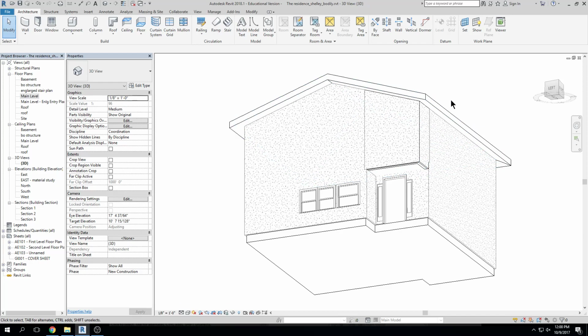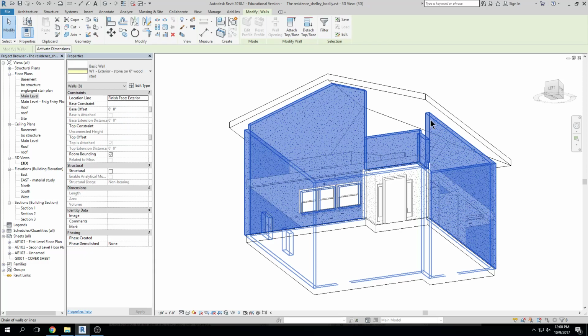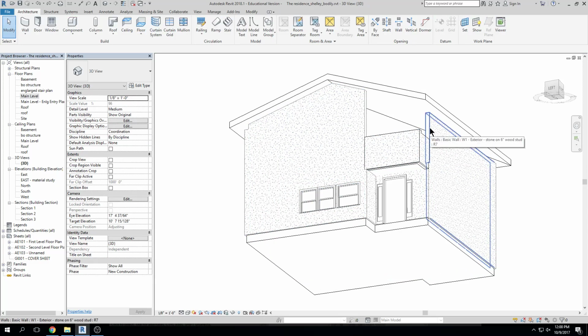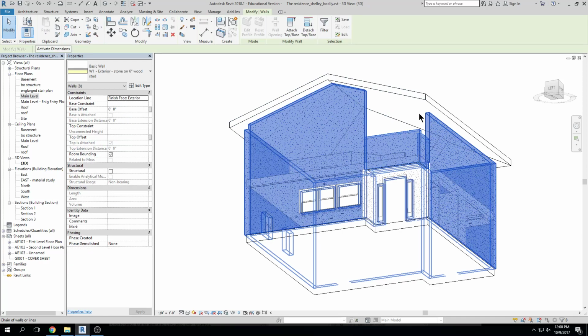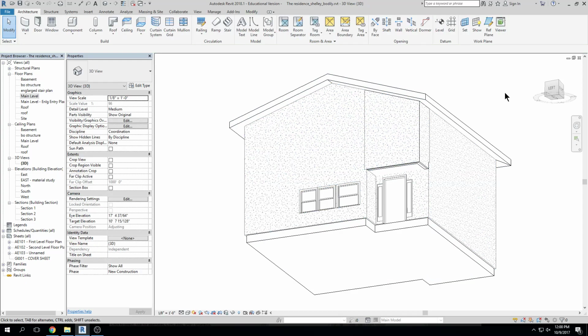The object. Yep, that's a good question. Let me undo, because this is always a tricky thing, right? I hover, I'm highlighting it blue, but I'm not clicking, but I'm on the object. I tab, whatever is touching that object in the chain, it selects, and I click. I don't move my mouse. Click. If I hover and I tab, and then I move my mouse, it essentially breaks that connection. Yep, hover, tab, click, attach, click, and all those walls go up to the top.